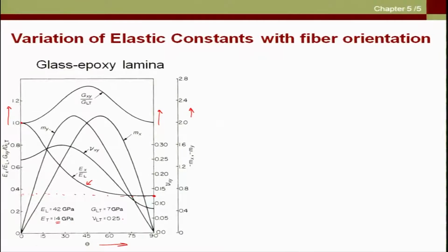So, this is one important observation, that for glass epoxy, Ex continuously decreases, and it achieves a minima, and the minima value is same as that of Et.